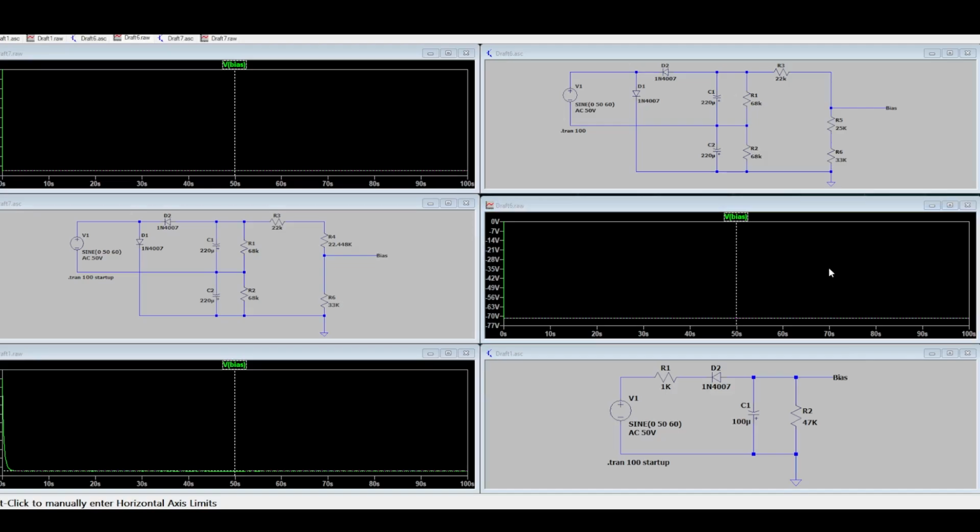And then this one, you can see we have negative 71.31 volts, which means we can run the tubes at a colder bias. So we can get as hot, basically, as we otherwise would get, a more positive voltage, but we can still throttle the tubes and run them closer to cutoff to save them from being in a situation where we're going to get a thermal breakdown of the tube.